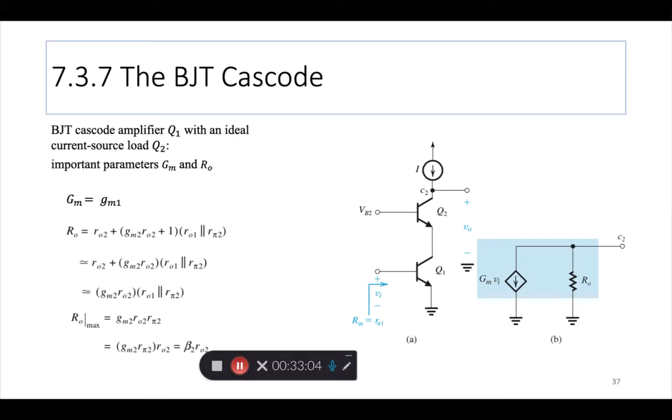Even before we talk about double cascoding, we saw that you can cascode both the gain cell and the current load source cell. In fact, you have to do both. You have to add two more transistors to get the real benefit. Now, if you do double cascoding, you add three more. So we have seen all that.